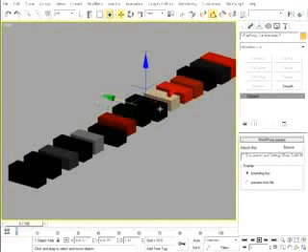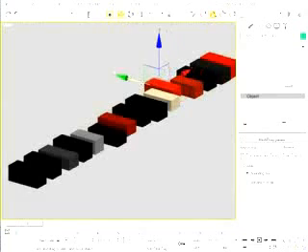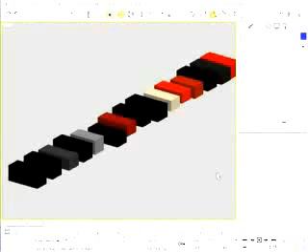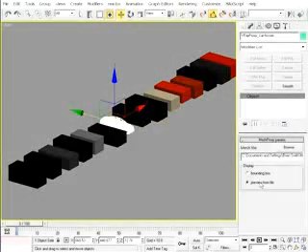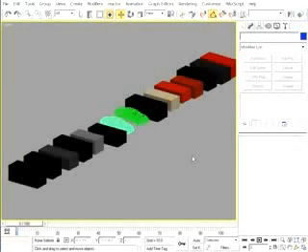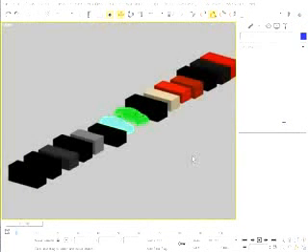And being able to move, rotate, and scale these proxies individually is often necessary and something I couldn't do if I exported them as one single proxy. Because when I load the proxies, all the cars would be locked in as one object. Not only that, the materials of the cars would be altered in an undesirable way because you can't create a single proxy file of multiple objects if those objects have different materials. If you do, only one of the materials will survive and all the objects will get that same material.